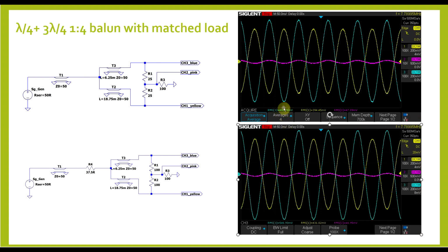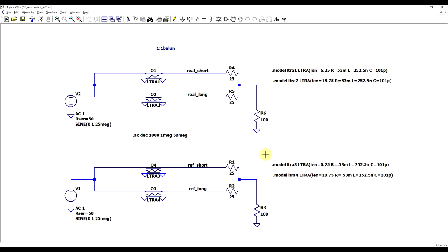So rather than getting 500 and 400 millivolts, we are getting 500 and almost 50 and 430 millivolts. So we still keep our imbalance. So if this is a problem of losses, it's not a problem of resistive loss, it's a problem of transmission line dielectric loss. And to finish the investigation, I made one final set of simulations.